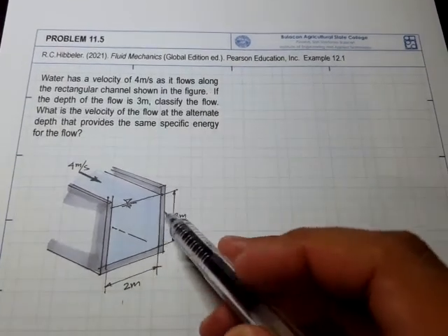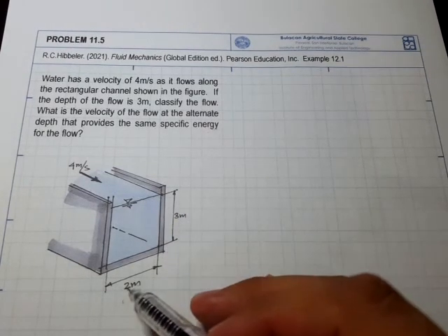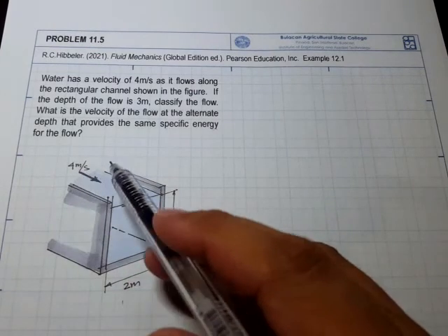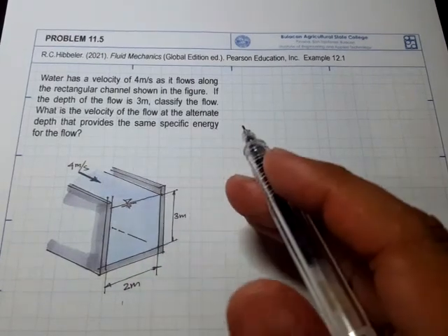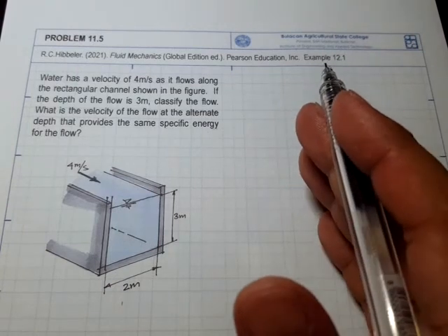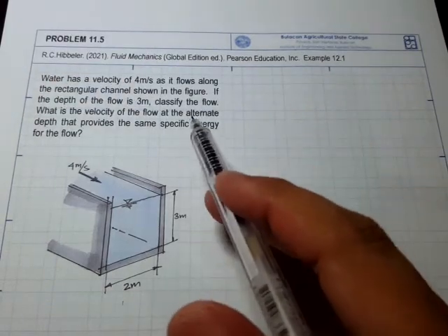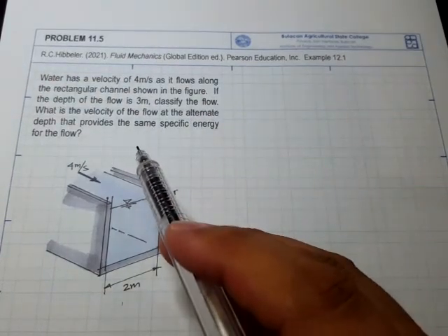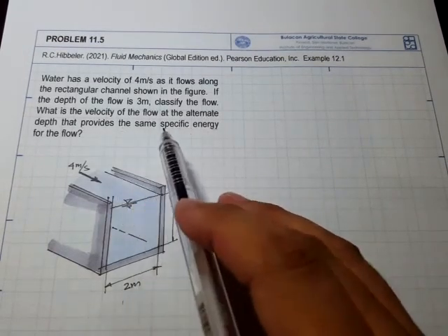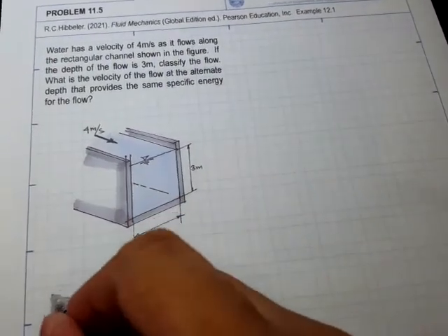So here's our rectangular cross section, and the depth is 3 meters and the width is 2 meters, and we have a flow velocity of 4 meters per second. We are asked to classify the flow, whether it's in the subcritical region or supercritical region, and also to provide the alternate depth for that same specific energy of the flow. Okay, so for the solution,